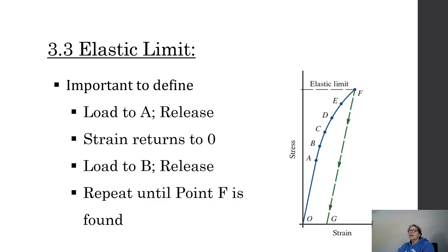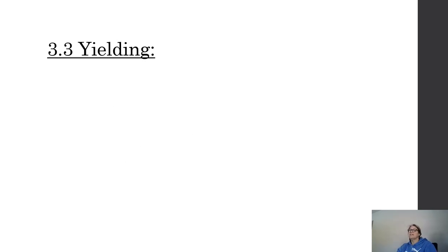Anyways, it's just loading and unloading and unloading. And to find that elastic limit, where do we stop? You load and unload, you load and unload. All of a sudden, when you come back down, it does not end up at zero strain. It ends up with that permanent set. And that's the point. You found that point of elastic limit.